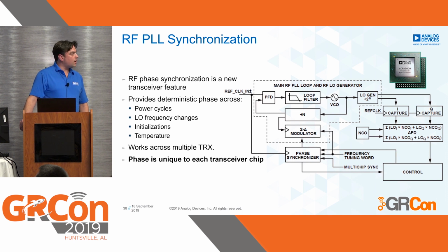It works across multiple devices in a multi-channel system. What we need to say here is that the phase is not zero between all of them, but it is fixed, and it's consistently fixed. So each of those transceivers does have a fixed phase.